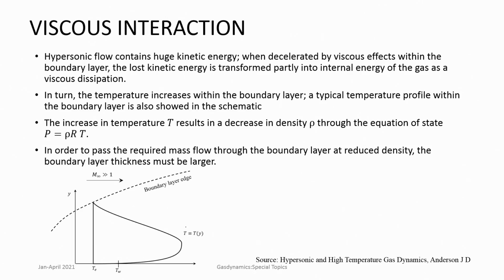So, that means the temperature near the wall will increase significantly. When temperature increases, correspondingly density decreases, and therefore what you get is that in order to pass the same mass flow rate, you need much higher thickness, or the thickness required becomes much higher.